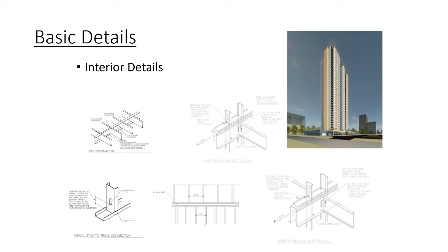In the upper row, furthest to the left, we're looking at lateral bracing of the floor joist system, cold-formed steel C-shaped joists being laterally braced by a combination of flat straps, top and bottom, and then solid bridging.